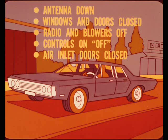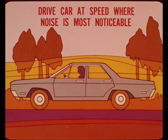Also make sure the radio and any blowers are turned off. Set the heater or air conditioning controls on the off position and move the air inlet doors closed. Drive the car at the speed where the reported noise is most noticeable so you can get an idea of the kind of sound you're concerned with. Sometimes a change in wind direction will vary or stop the noise, so be sure to check the effect of driving into and away from the wind.